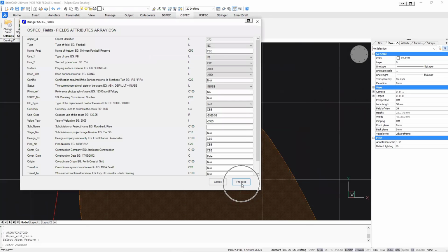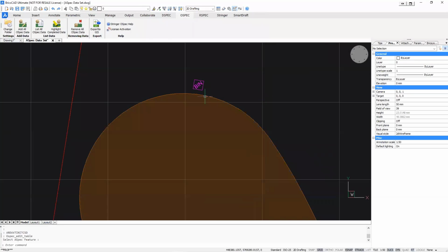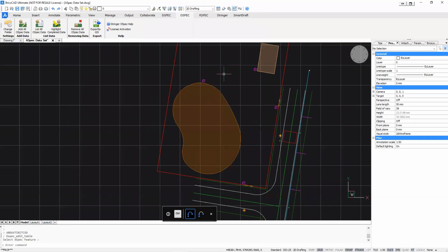If you don't hit the proceed button, it's not going to retain anything, because the only other option is cancel, and exiting out of this will act the same as a cancel. So you just make sure you're hitting that proceed button to save all of your changes. Now, if you come into one of these and you believe that everything has been filled in correctly, it's just a neutral file or something, you can hit proceed to attribute all that information into the object and just move on.